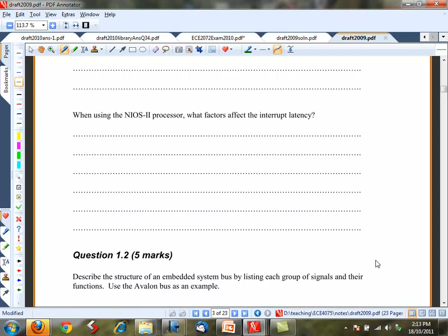Yes, so in the software, it's got to make a decision where the interrupt source is. I mean, there's IRQ 0 up to 7, I think, on the processor. Now, that can be done in software, which happens as a default, but you can, when you instantiate the processor, incorporate an interrupt controller that does that in hardware.